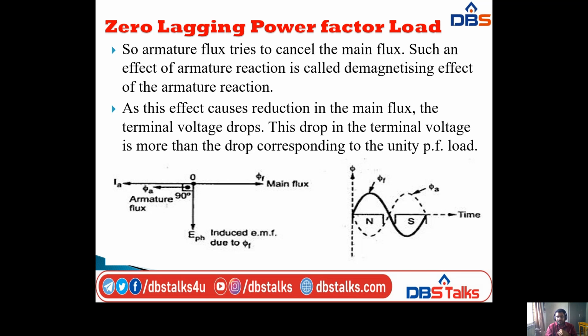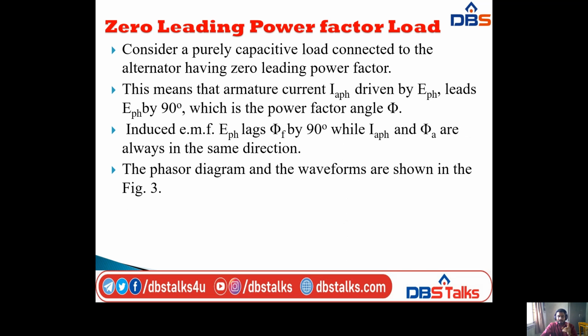So this drop in the terminal voltage is more than the drop corresponding to unity power factor load. Okay. And next, consider a purely capacitive load, that is, for the leading power factor. For the unity power factor, we considered a resistive load, for the zero lagging power factor, we considered an inductive load, and for the zero leading power factor, we are considering a purely capacitive load connected to the alternator.